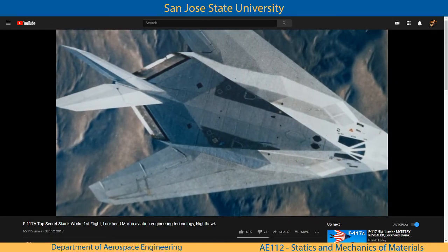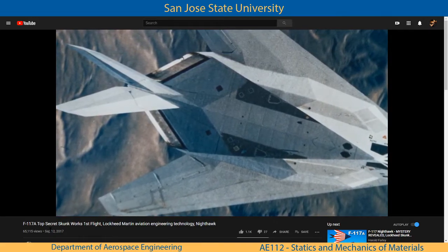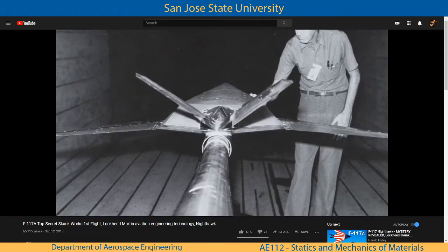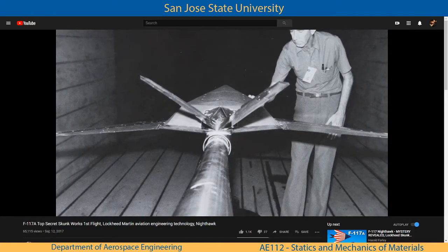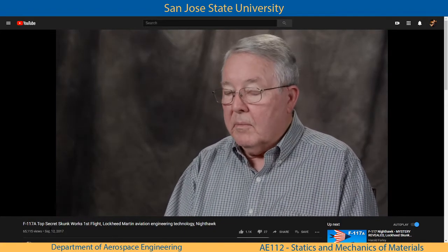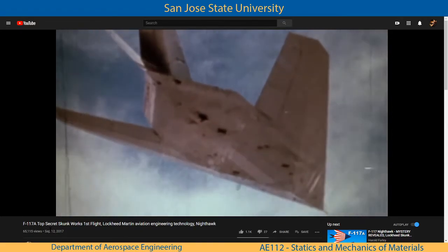Based on that information, we realized that the tail fins on the airplane were considerably too small. The wind tunnel data, I don't know how a mistake was made. Somehow, I believe I heard that they didn't take into full account the sting, the pole that you put an airplane on in a wind tunnel, contributes to stability. And I'm not sure that's the case. At any rate, they came up with a figure that they said we were going to be more stable than we really were. So the fins were too small, and that was the big discovery on the first flight.